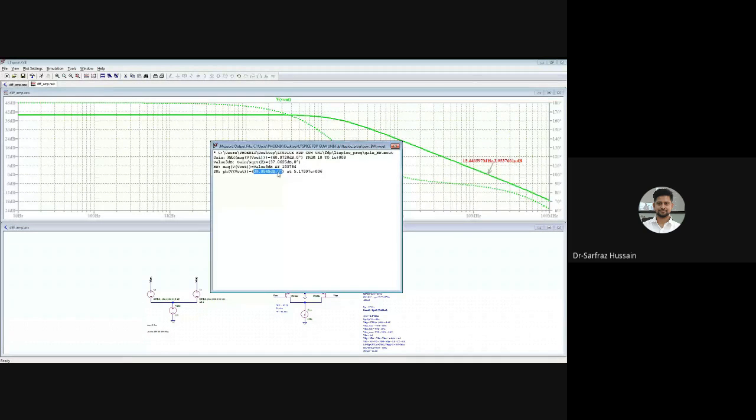Okay, so sorry, at 0 degree phase, it is showing 39. And what is the value that we are getting? So we are getting this much phase. And here you can see the gain. So the gain is this. Then the value in 3 dB is this. Gain divided by square root, so the minus 3 dB point is this one. So 37.06, this is the minus 3 dB point, and we can find out the bandwidth, which is this 15.37, right?